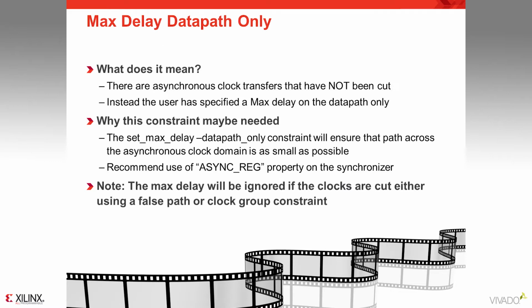The set max delay datapath only constraint can be used to constrain the data path on an asynchronous clock transfer, instead of cutting the analysis with a set clock groups or a set false path constraint. Merely adding a set max delay datapath only is not sufficient on paths across asynchronous clock domains. You must ensure that a proper failsafe mechanism like a synchronizer or a FIFO is present for the transfer to be safe.